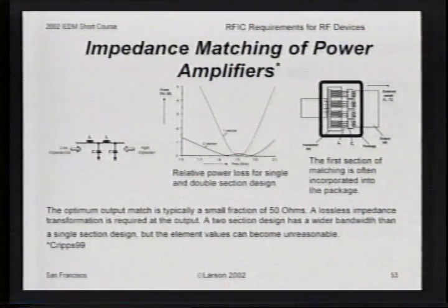One of the things that power amplifiers require is an extremely high-quality passive device technology supporting them, because although we tend to work in a 50 ohm environment in the world, the power amplifier likes to see a much smaller impedance, just a few ohms typically. And this requires a very high quality inductor capacitor network at the output. And very typically, this high quality inductor capacitor network is realized off chip, because even though the inductors have gotten very, very good on an IC process, they're still not good enough to realize the performance that's required in a typical PA application.